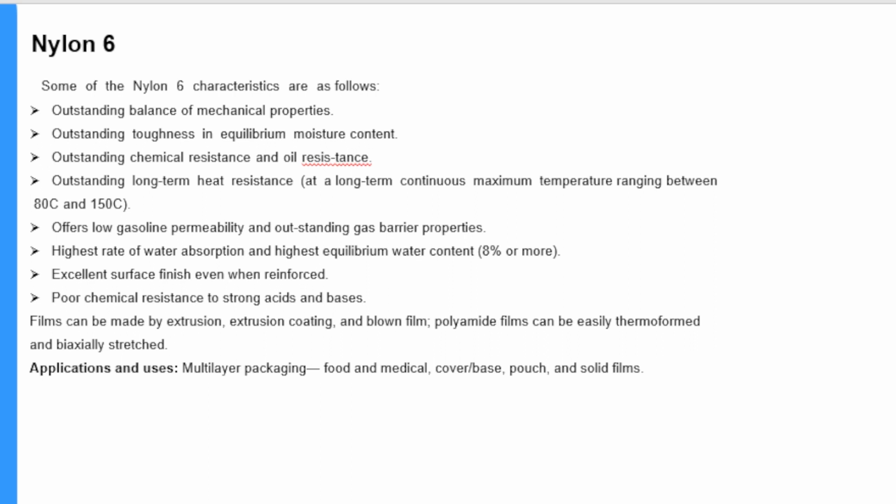Excellent surface finish even when reinforced. Poor chemical resistance to strong acids and bases. Films can be made by extrusion coating and blown film. Polyamide films can be easily thermoformed and biaxially stretched. Application uses: multi-layer packaging, food and medical, cover base, pouch, and solid films.